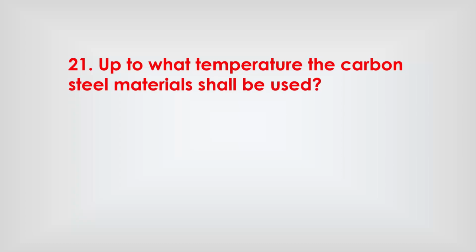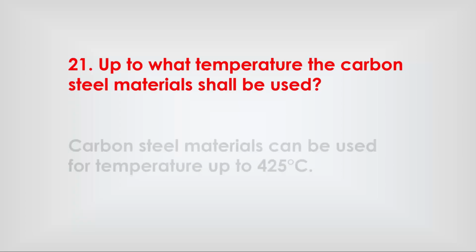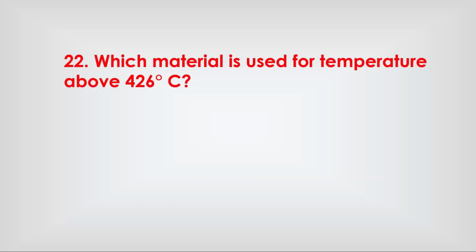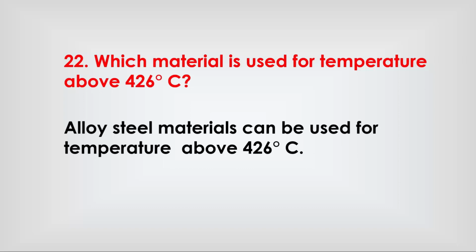Up to what temperature shall carbon steel material be used? Carbon steel materials can be used for temperature up to 425 degrees Celsius. Which material is used for temperature above 426 degrees Celsius? Alloy steel material can be used for temperature above 426 degrees Celsius.